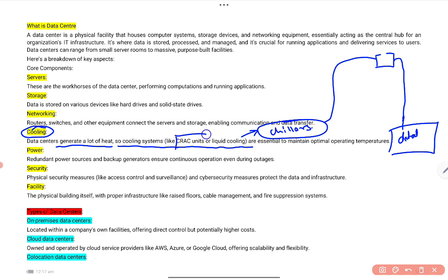And this is the air unit. This is the computer room air conditioning unit, located in individual rooms in small areas, and the chillers are located on the terrace to provide the cooling water through this header pipe, or we can say for the DAHU, data hall air handling unit, or fan coil unit, FCU. CRAC and liquid cooling are essential to